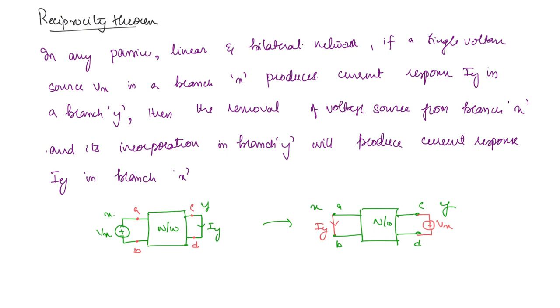One thing that you need to know here is if we are talking about a voltage source here, then this is basically called the excitation. So it is exciting and there is a response, stimulus and response, you can take it like that. So now when this excitation is interchanged, response will remain as it is, but the excitation and the response should be such that if one is voltage, the other should be current. If one is current, then the other should be voltage. You cannot say the same thing about voltage and voltage.